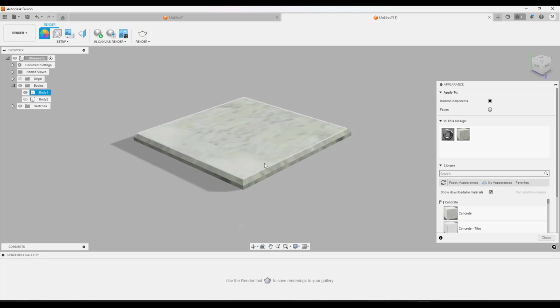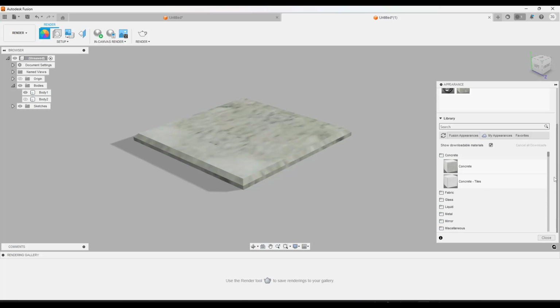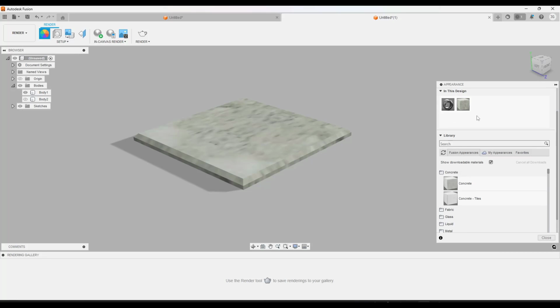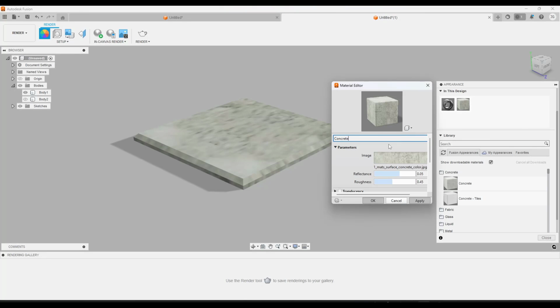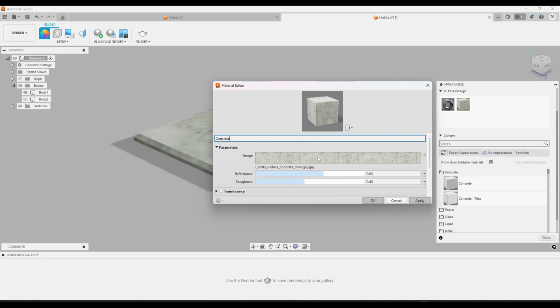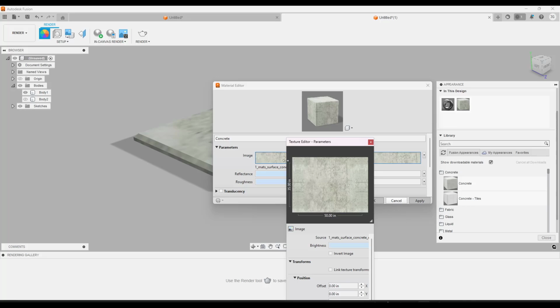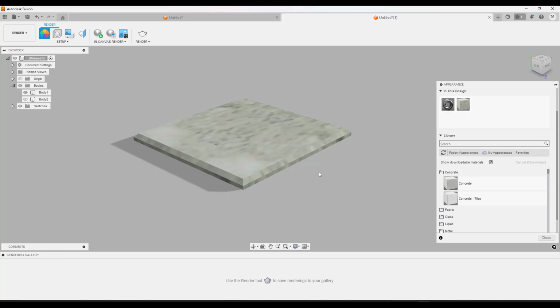material size and scale. There are really 2 different kinds of materials in here. There are materials like this one that are basically taking an image and tiling it across your surface. If you right click on this, edit it, and go into your advanced settings, you can actually see the images that are being used to create that material. Notice this is just retiling this image over and over again. And we'll take a look at creating a custom material in a second.